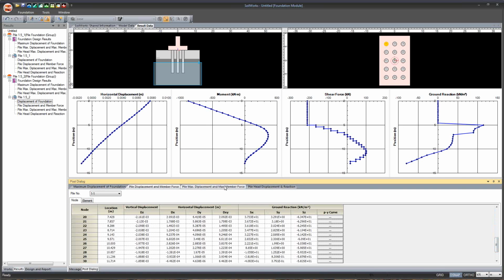Okay. Now this is, for example, the pile 1 location. Now here what exactly you get, as I was saying, after the analysis we get the PY curve at each location of the pile. Initially we inputted the soil material behavior, but after the application of load, what spring stiffness a structural engineer should provide in structural software like Midas Civil can be directly obtained from here. For example, first you got the maximum displacement, then you can see that pile number 1, which is the outermost pile.